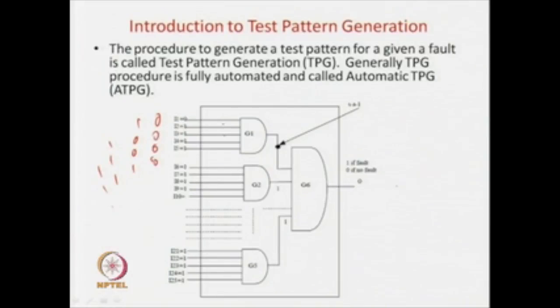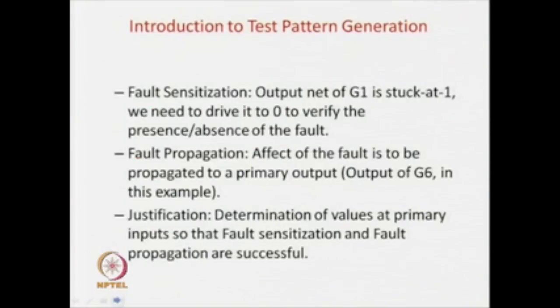So, the first is called fault sensitization. What do you mean by fault sensitization? We say that the output net of G1 is stuck at 1, we need to drive it to 0 to verify the presence or absence of a fault.